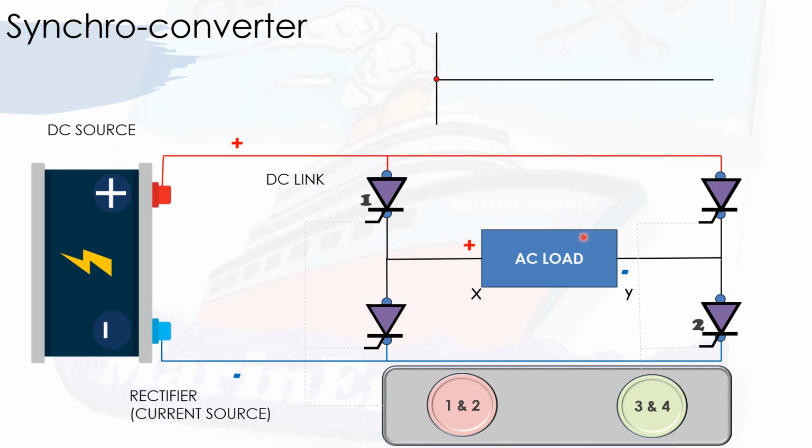In this diagram, I have replaced the four switches using silicon controlled rectifiers. And I have used a programmable controller, which is responsible for firing each SCR. The SCR is a three-terminal device similar to a diode, which means it allows current flow in only one direction. But unlike an ordinary diode, you have to supply a gate pulse, and only then will it start conducting. This conduction will continue until the current flow becomes zero or falls below the holding current of the SCR.